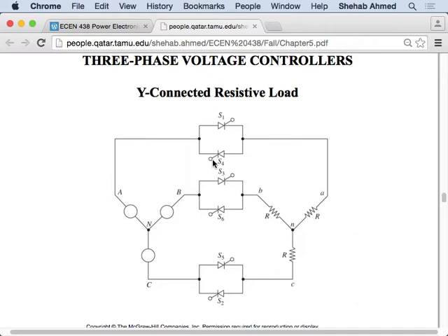In 459 we will study what's called symmetrical components. Symmetrical components are a mathematical theory that can take three-phase voltages and chop them up into components. If you're applying a balanced set of three-phase voltages, symmetrical components theory does nothing. Imagine your three-phase voltages coming into a box that has your symmetrical components coming out. Symmetrical components are voltage components of different frequencies. So if you put in three-phase balanced voltages, you will get three-phase balanced voltages at the output of that box. That's all you'll get, right?